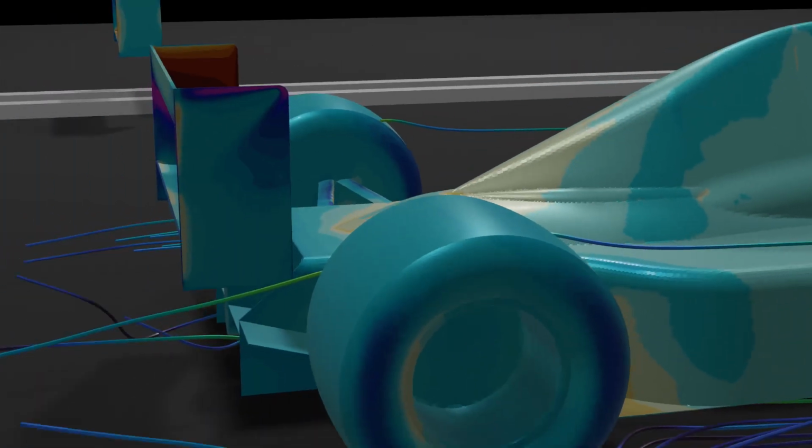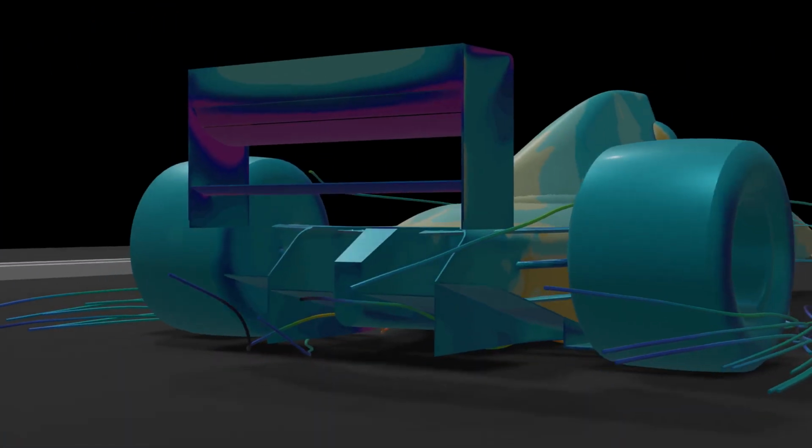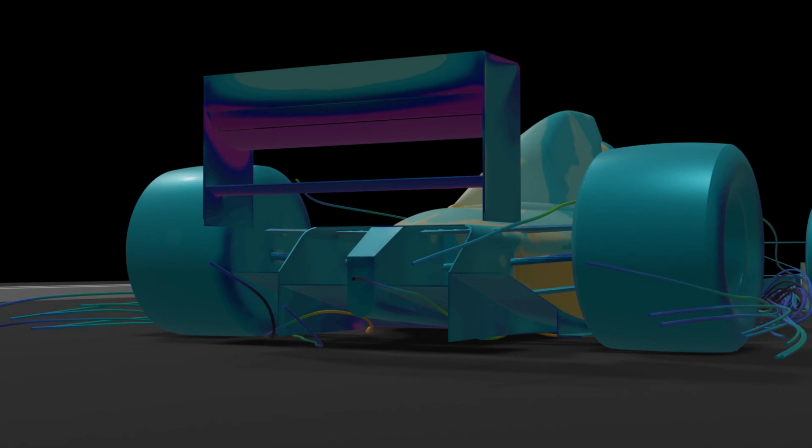Now the rear wing. This was way more difficult than I thought it was going to be. The approach I took for this was to run half wings in simulations by themselves, which meant I was able to iterate much quicker. I was able to quickly build the lift numbers, peaking with a design that would give me about 1460 newtons, which I thought was close enough to the theoretical 1600 newtons stated by the paper.